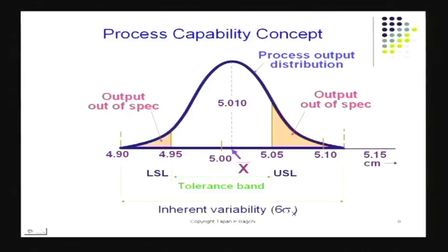This gives you an accurate process. If the average value of output coincides with the target of the process, that's a requirement, you end up with what we call an accurate process. A precise process is going to be one that has a tight distribution. A precise process always has a tight distribution. And we have some means by which we can specify these different characteristics, accuracy and precision.